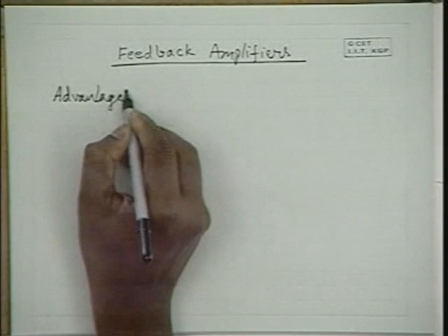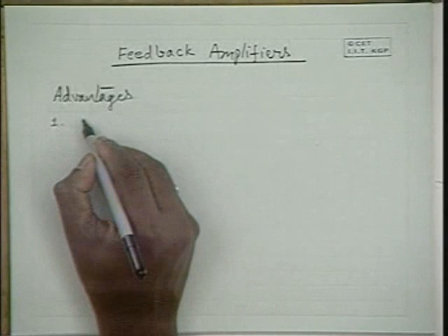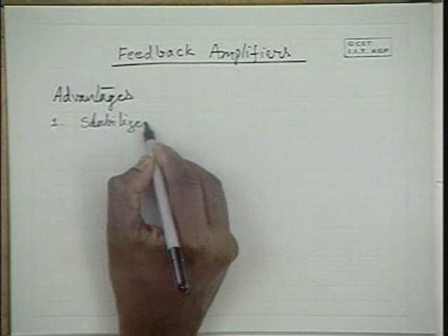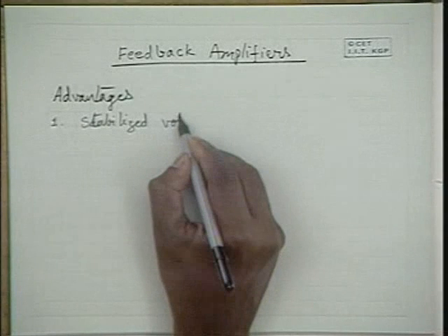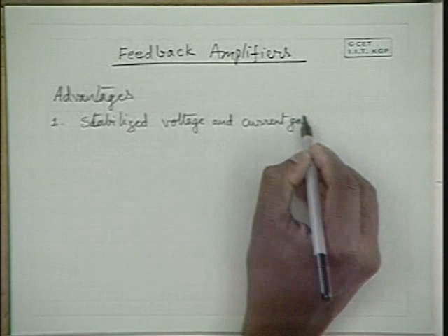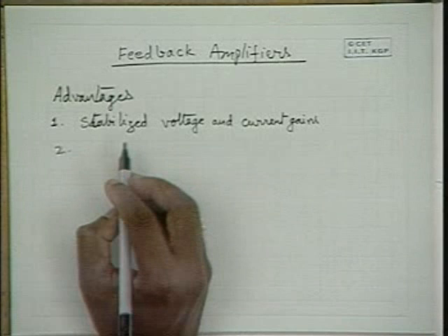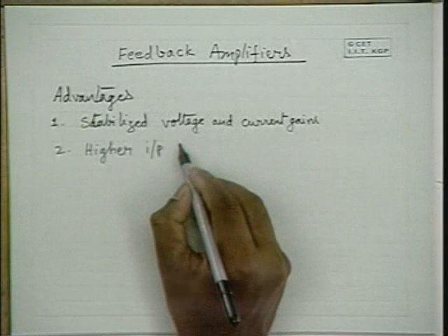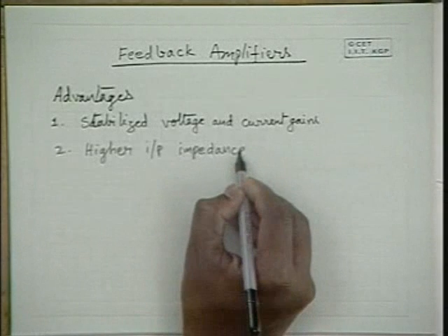So in turn we get some advantages if the feedback is negative. Negative feedback gives rise to the following advantages. Number one, stabilized voltage gain, stabilized voltage and current gains. Then we have higher input impedance than the input impedance without feedback.